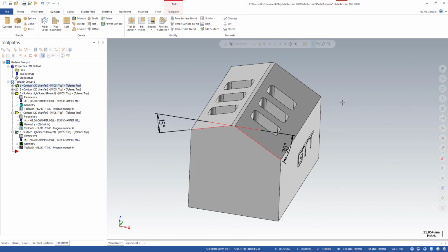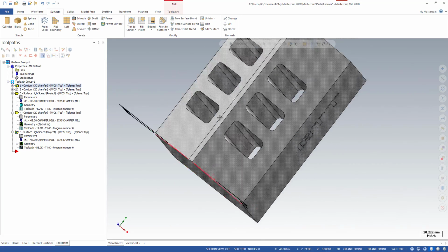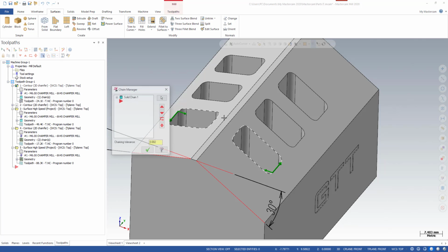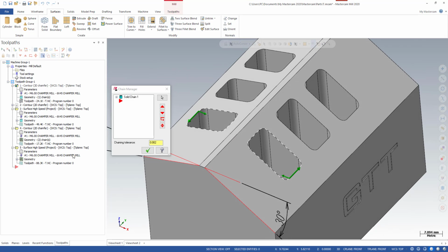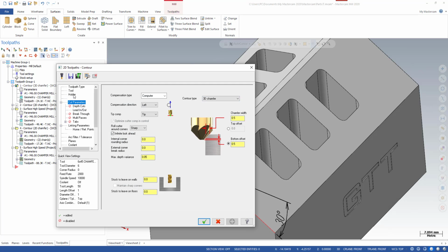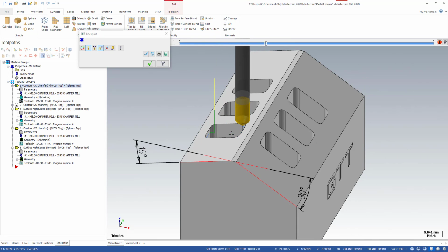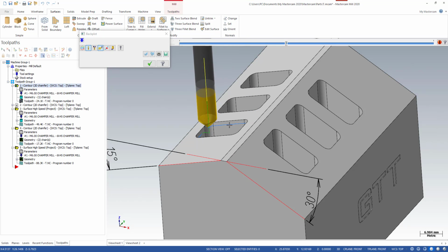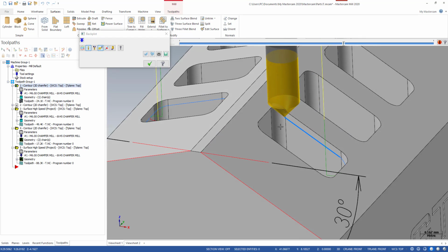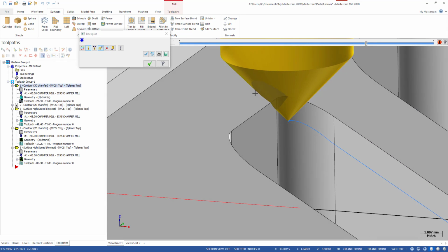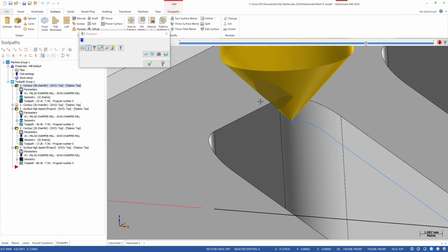We go back to our part. Okay, and see it again. You can see the first toolpath, I use a 3D chamfer. So I select this chain and this chain, and in the cut parameters here, I select 3D chamfer. I input the chamfer width and the bottom offset. But the problem is, for this toolpath, Mastercam doesn't know what the part is, so it doesn't care how much material it will take. It just follows the curve, something like this. So we got a bad result in this area. You can see we have a very large contact error, so that's why we have a very big chamfer.